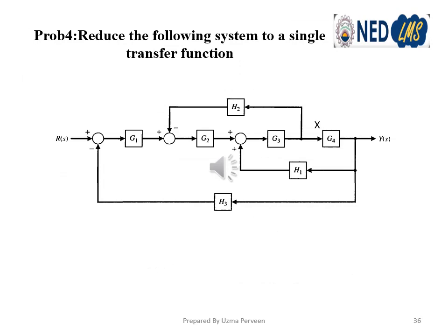Okay, this is the next problem after simplifying the previous block diagrams. We can solve this block diagram too. We can see here that the first minor loop with the forward transfer function G3, G4 and feedback transfer function H1 cannot be solved because of the point X in between G3 and G4. So to solve this feedback loop, first we have to move this point X beyond the block G4. If we move this point X beyond the block G4, we have to add a block 1 upon G4 cascaded with the block H2.